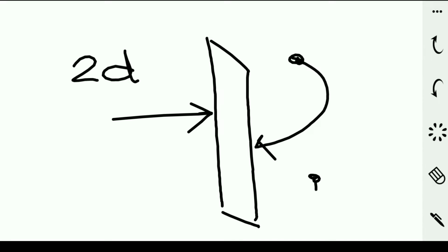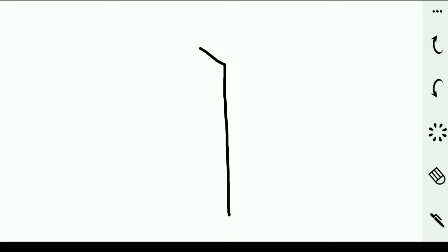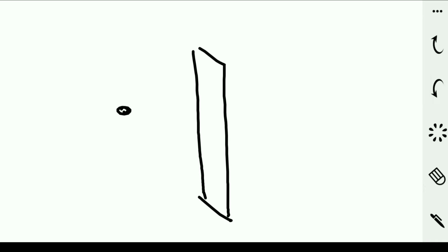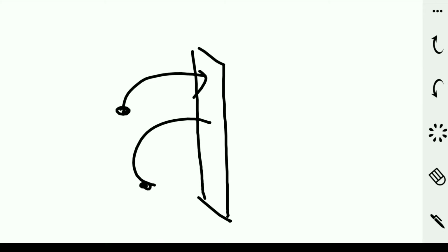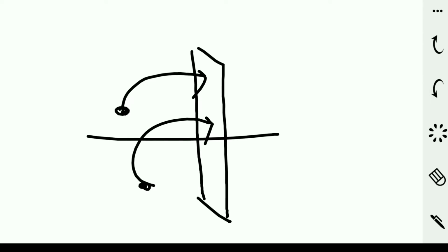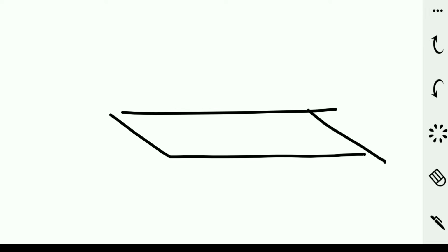Like something is given, a point is given in front of a vertical plane or behind a vertical plane, or below the horizontal plane or above the horizontal plane. So this kind of thing works when we understand it clearly. Like a point is given, which is above the horizontal plane, so it is fixed on vertical plane, we should understand. And if it is in front of vertical plane, we have to rotate it and bring it to the vertical plane.